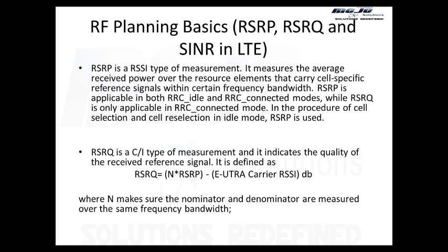So moving on to LTE, in LTE coverage is measured by RSRP, reference signal received power. Whenever we are talking about signal strength, the unit of measurement remains the same. It is dBm on the logarithmic scale, and watts on the linear scale. You should understand what a logarithmic scale and a linear scale are.